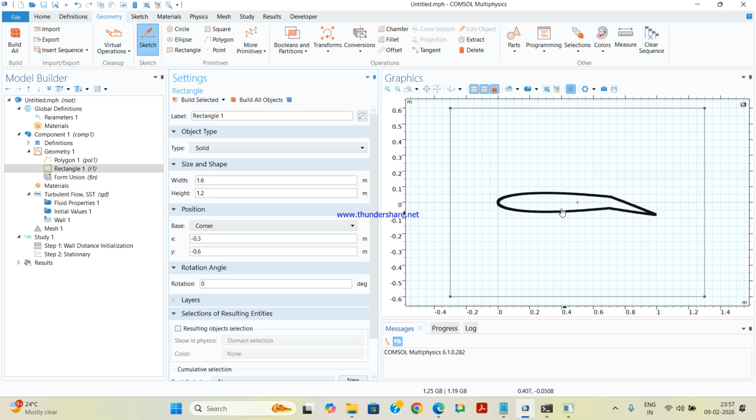Okay, now we have to consider this area only as air, and this will be empty. Here this is the inlet, and that will be the outlet. So air will pass through. You can consider this rectangle as an air tunnel. So here the air will be flowing and coming out through this, and for that particular case we are going to check the velocity distribution along the line, the airfoil periphery.